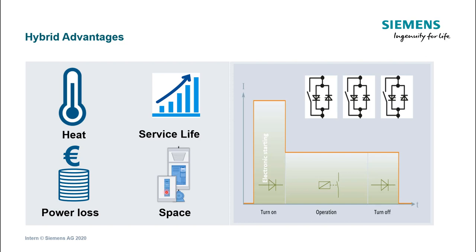All you're doing is using a motor at full speed, and if you don't have that mechanical bypass contact in there, you're using thyristors constantly, which means there's a lot of power and heat loss. So if you're using a motor at fixed speed at 100% of its operational capacity, then a soft starter would be the correct device to select. If you're looking at making an energy saving, you can reduce the speed of the motor by selecting a drive and make energy savings in that respect.